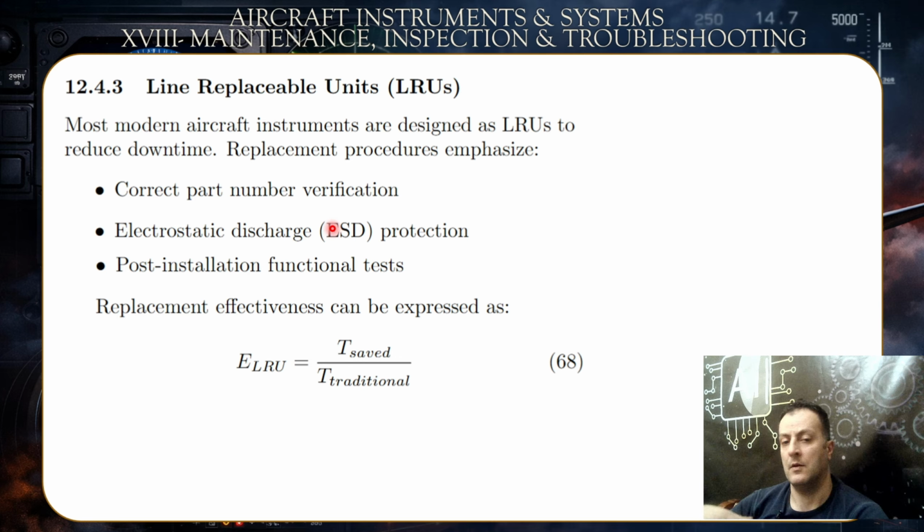This can be done by wearing the anti-static wrist strap, which is a strap around the wrist that is a good conductor for electricity. It would be connected to a ground bus so that while working with an instrument, any electrostatic charge within a person's hand would not go into the instrument, damaging it.